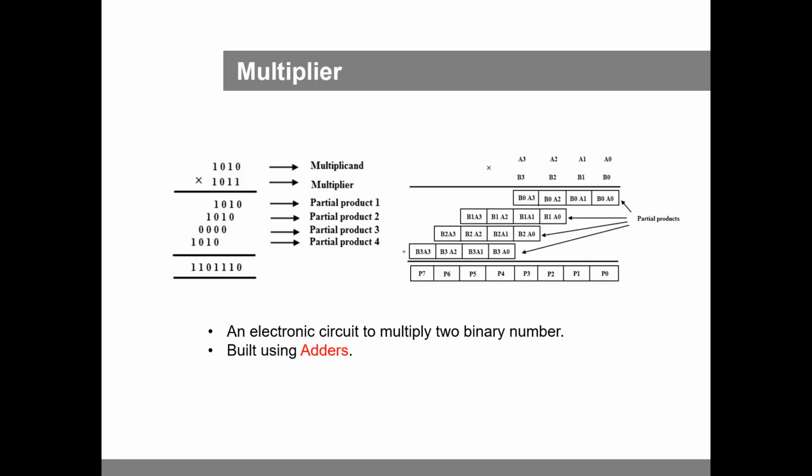Hi, this time I'll introduce the multiplier. The most basic form of a multiplier is the product of two binary numbers. This multiplication process consists of calculating the partial products and summing the shifted partial products. A multiplier is generally divided into a serial multiplier, a serial-parallel multiplier, and a parallel multiplier, depending on the format in which the data word is handled.